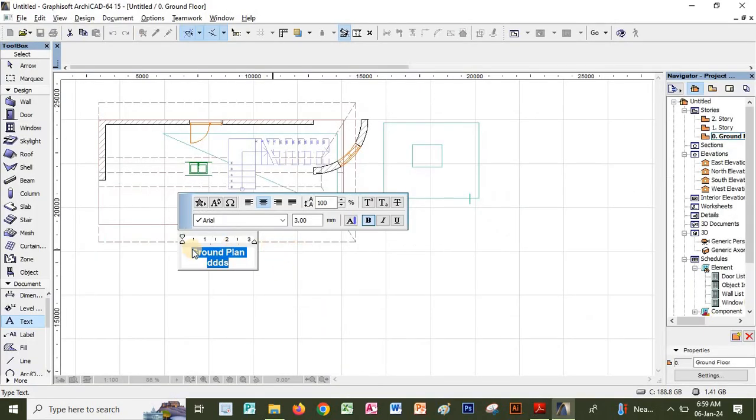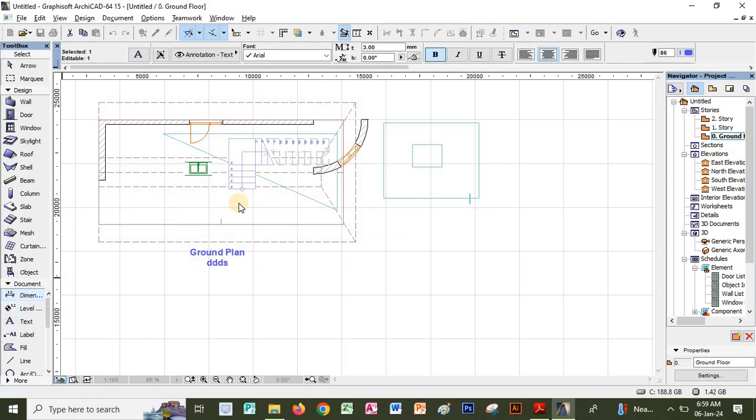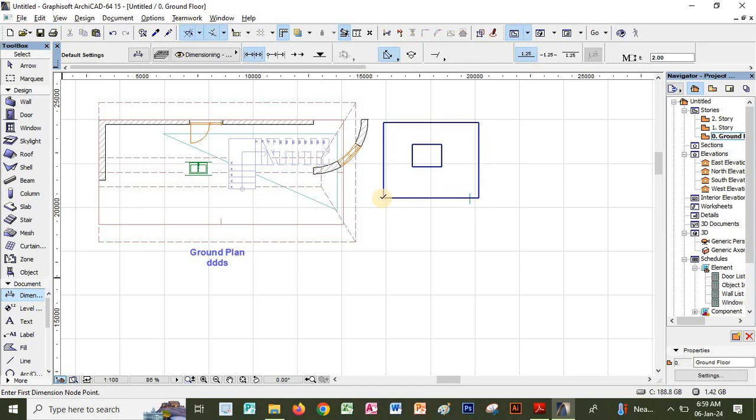Dimensioning, if you look just where we have the document and the text, dimensioning is there. So I can dimension my area like there, from here to here. You click where you want to add the dimensioning, click where you want to start and where you want to end, and then double click somewhere else. And it is going to be placed like that.